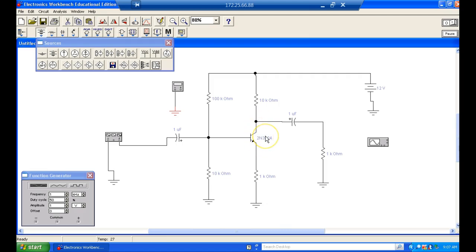The higher the voltage on the collector is, the closer it is to cutoff. So when I bring an AC signal or an audio signal in, if we get too high, the tops would clip before the bottoms. We'd like them to clip at exactly the same spot, and that would set our upper voltage we can put in. So we need to lower this voltage right here. What could we do to our design to lower that voltage?